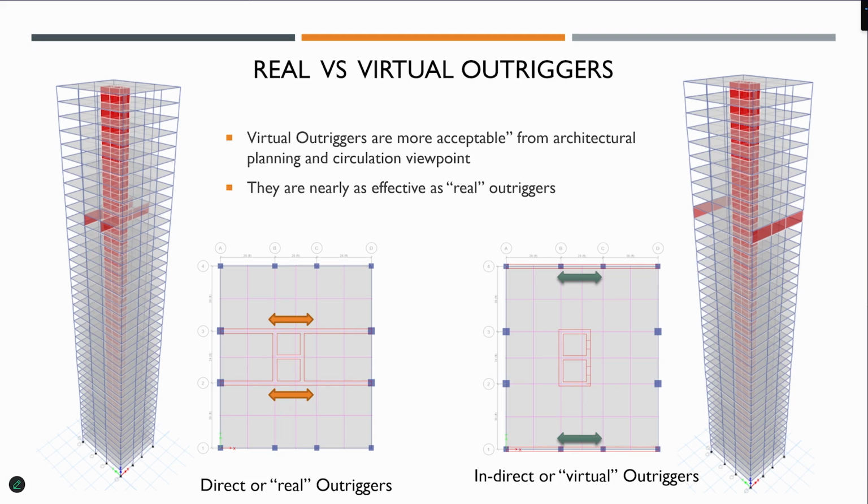Of course, it is not as effective because there is some shear flow between them, and then there's some deformation in the plane of load. You have to make the floor thicker to make sure that it works like a box. But the good point is that you can move these outriggers outside of the view. Now, in this direction you need them here, but in this direction you need them there. You need them in both directions, not only in one. Because for this direction, these walls will be fine. For movement in this direction, you need to put them outside.